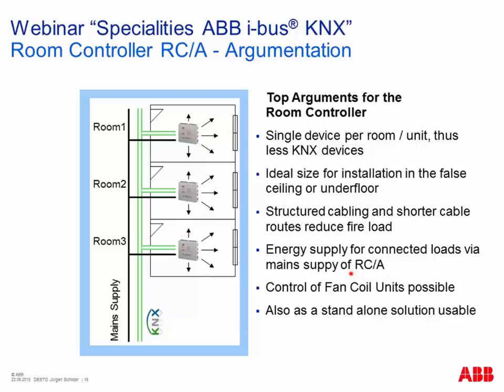I mentioned already also fan coil units can be controlled, so all the traditional loads you have in a room can be linked here. And if you want, it is also possible to use a room controller as a standalone solution. After programming all inputs and outputs in the device via KNX and ETS, you can disconnect the ETS, or the KNX cable, and then it would work thanks to its own power supply as an individual device in the room.